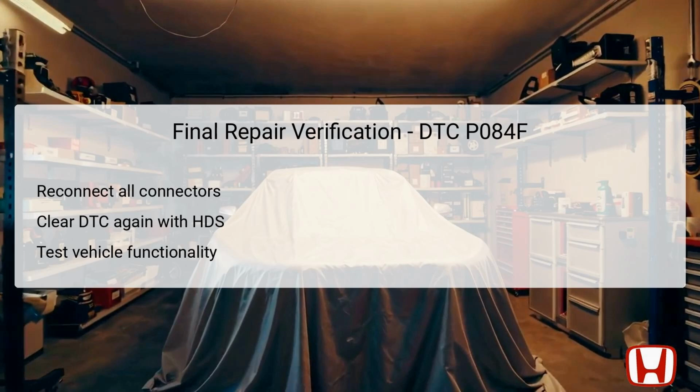Subsequently, conduct a functionality test by operating the vehicle under conditions that previously triggered the DTC. Proper functioning of the transmission should now restore normal operation, and the check engine light should remain off. If DTC P084F reoccurs, further investigation will be necessary to identify any unresolved issues causing the error code.